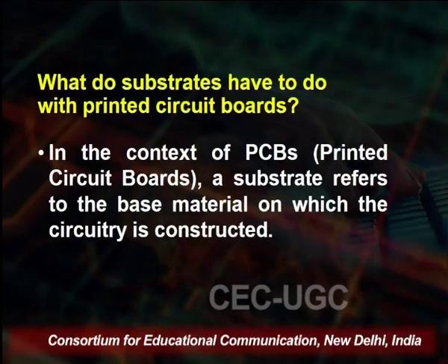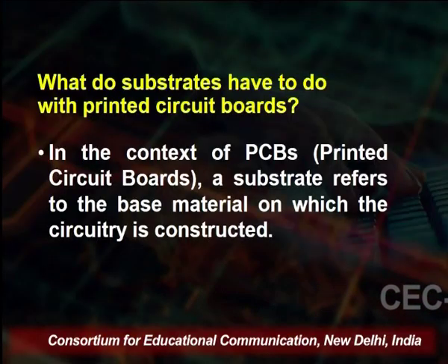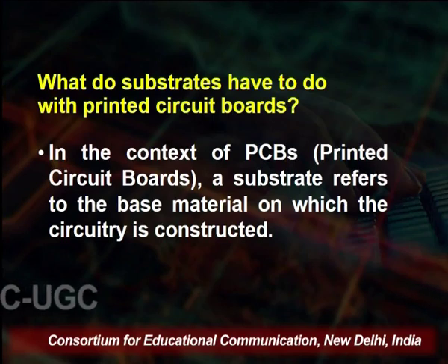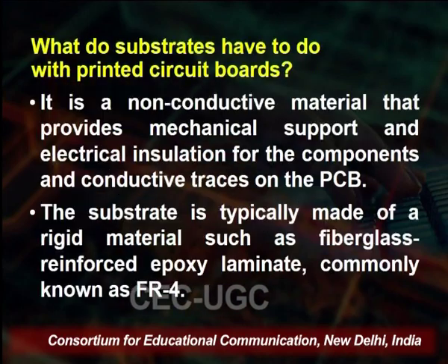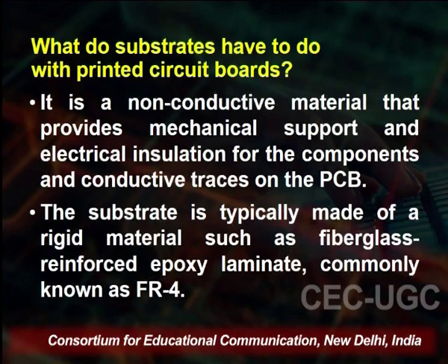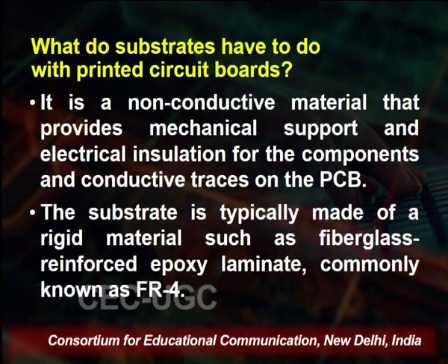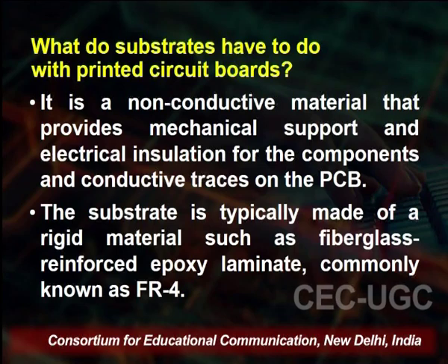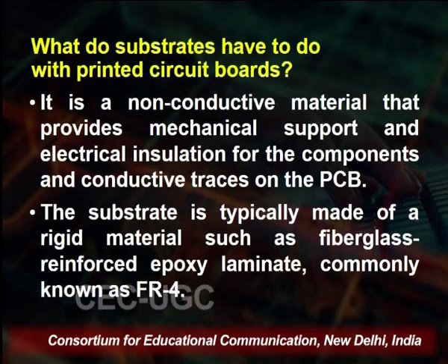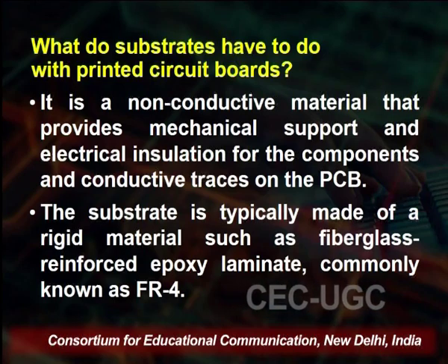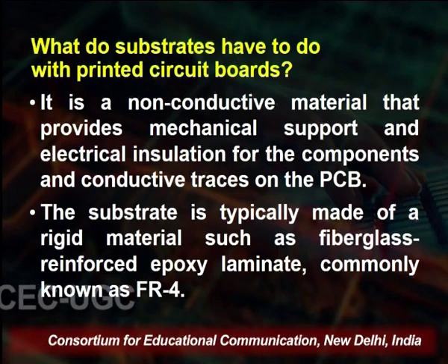transparency. So now, what do substrates have to do with printed circuit boards? In printed circuit boards, we refer to the substrate as the base material where we construct the circuit, and it is a non-conductive material which provides mechanical support and electrical insulation for the components and the conductive traces on the PCB. As you know, the most commonly used substrate is fiberglass reinforced epoxy laminate, which is used commonly in laboratories as well as in circuit designing, known as FR4.